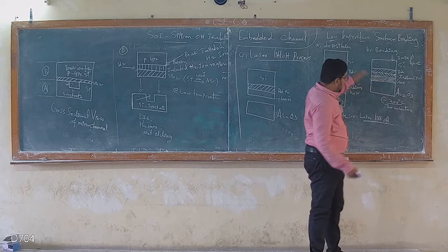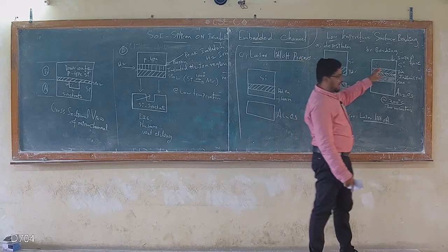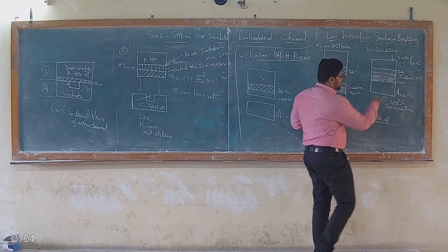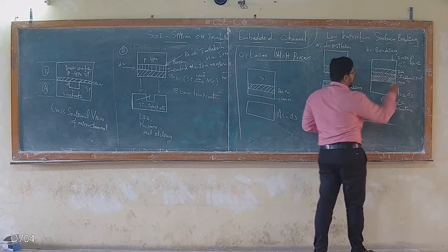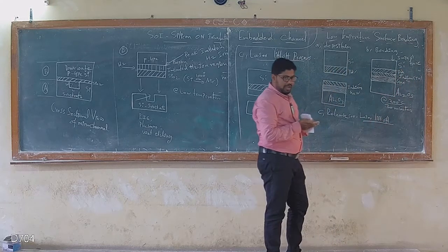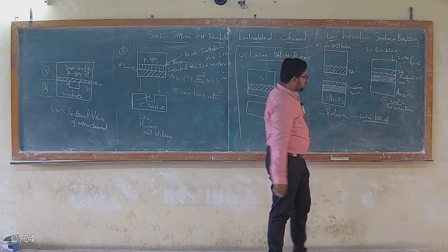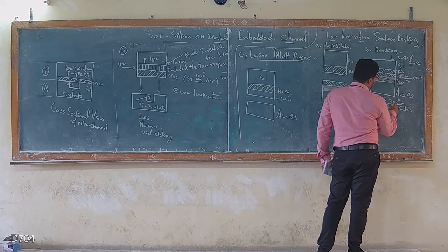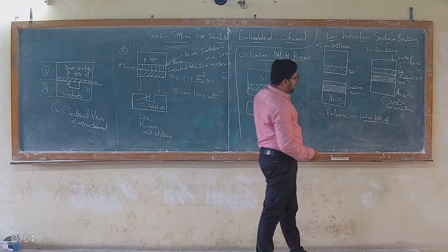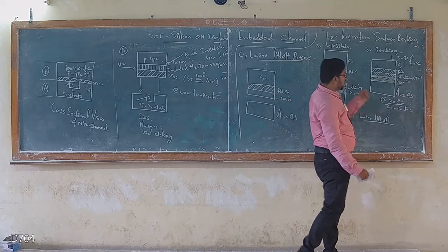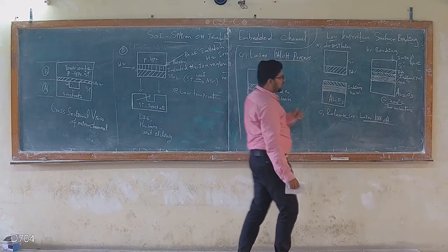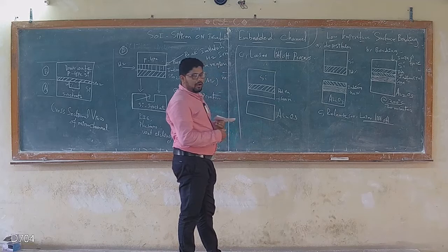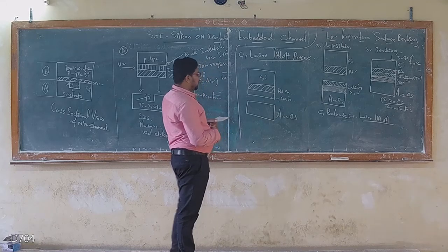Here, I'm going to press both sections with a mechanical force of 3 megapascals, with gallium arsenide carrying indium and silicon carrying palladium pressed face to face. Both surfaces are heated to almost 200 degrees Celsius with the mechanical force. The palladium and indium come into close contact and form a small melt between them.